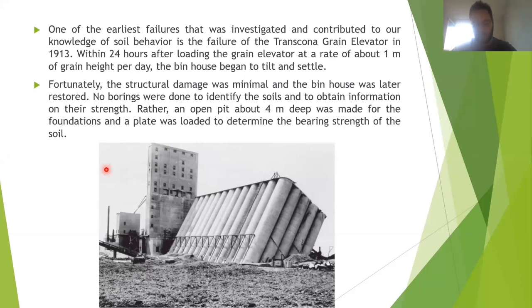Investigative borings are basically holes you drill in the ground, and you take samples from that hole, continuously sampling, and then you do something called classification of soil. We'll speak about that in 4 slides. Usually you take samples at the place where you expect your foundation to be.